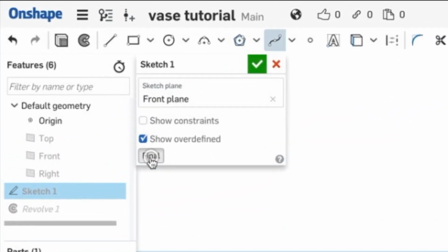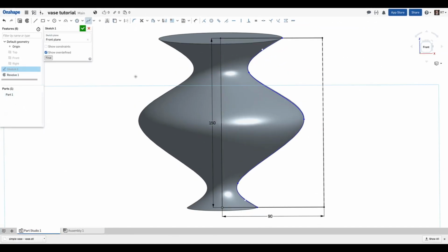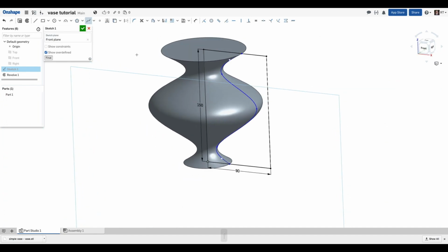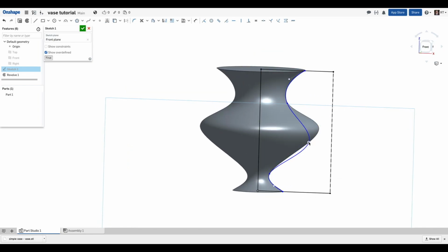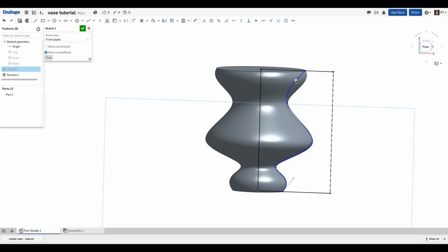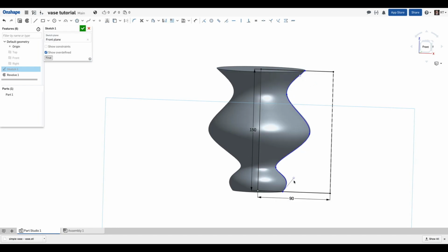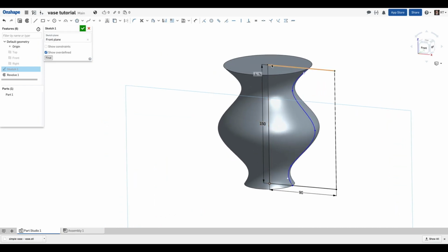The final button again shows you what it will look like when the revolve feature is placed on that. F will fit it to the view. Deselect spline. We can go in and shape this in here. These right here show the starting angle, ending angle up here. Basically, it's like putting something on a lathe that's spinning around this axis here.